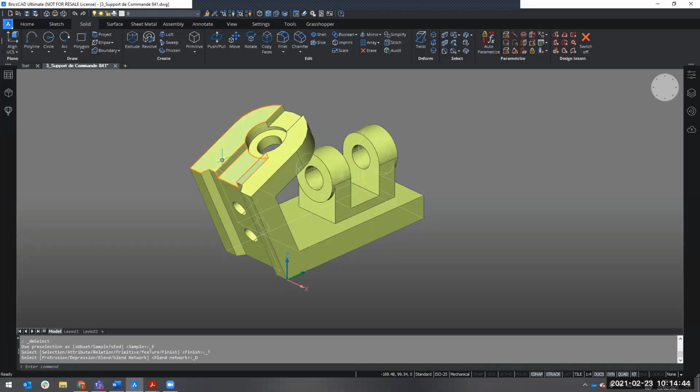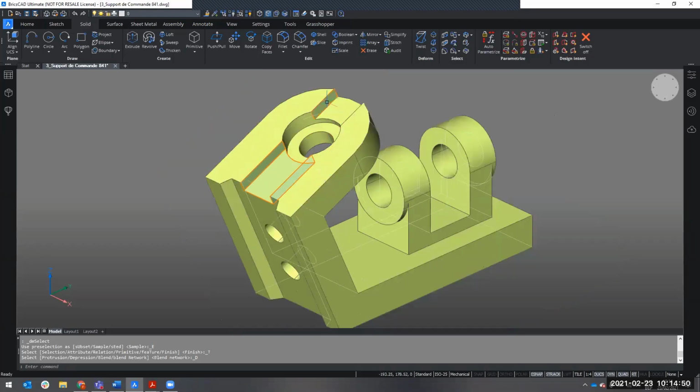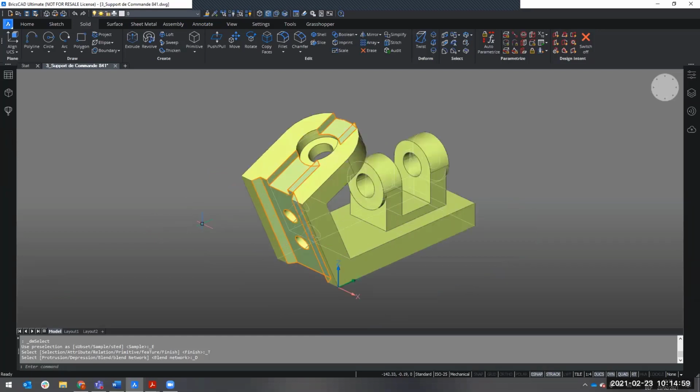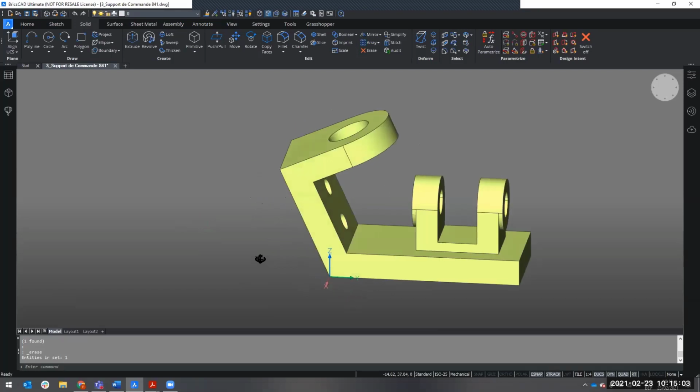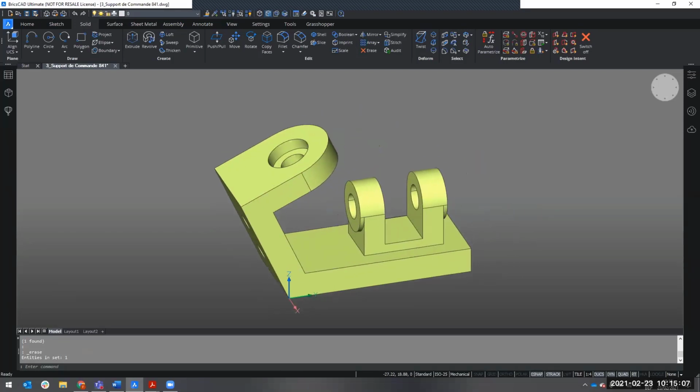And then you will select from one face where you hovered over, you will select all the connected faces in that depression. So you can also do it at the side here and at the side here, for example. And then if you have selected all of them, you can again press the delete key, and same goes here. The depressions will just go away and you will have a cleaner model.